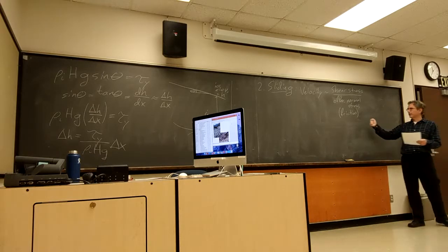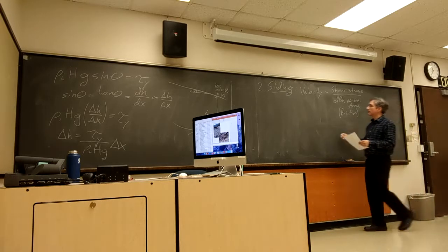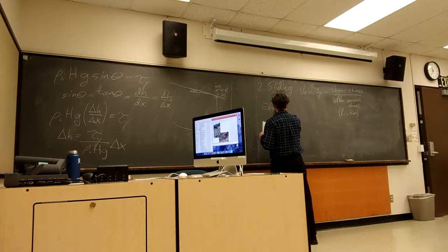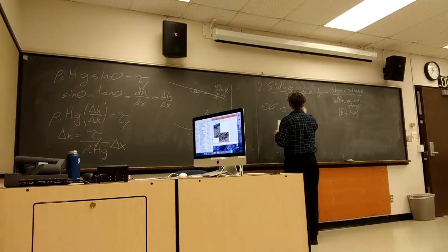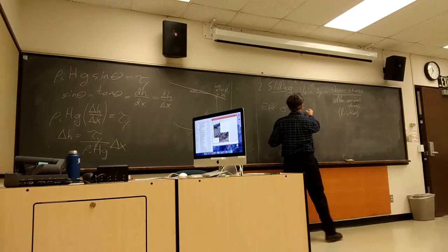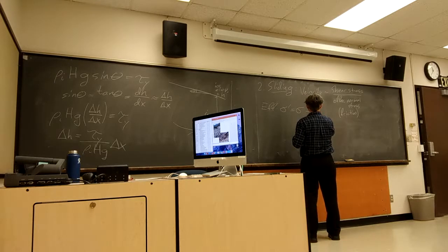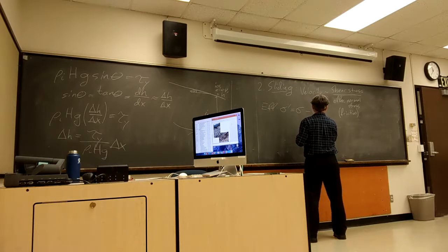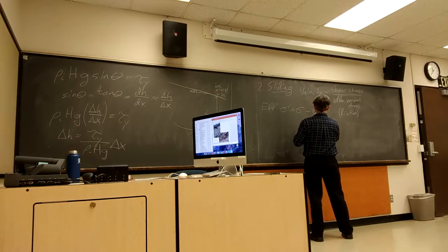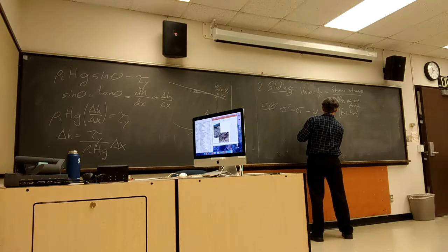The effective normal stress is going to be that due to the weight of the ice minus water pressure. Okay. Liquid H2O pressure.